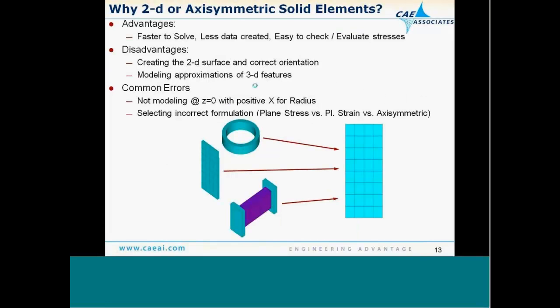So moving on from beams, we also have 2D elements we can look at, and 2D elements allow you to get a much faster solution. A lot of axisymmetric problems have no accuracy loss in running a 2D axisymmetric model if my loads, geometry, and materials are axisymmetric. It's much easier to post-process because we can look at the results directly on the face. We don't have to figure out how it's sectioned to cut open, etc.